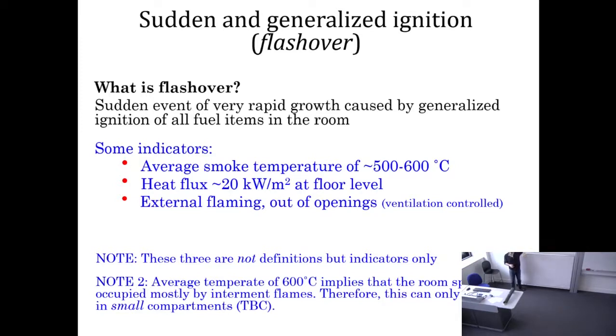At 20 kilowatts per meter square, any polymer will ignite. Any. It's just a matter of when. And probably some of them will ignite extremely fast, within milliseconds. Some of them might take actually a few seconds. Okay?